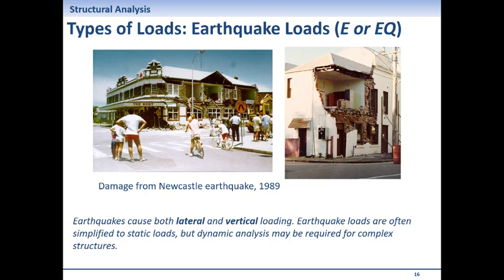Stress is something that happens inside a structural element. You've got a beam, you push it down, it flexes, and then not any stress, but flexural or bending stresses start to develop. That's a stress. Stress is always inside the material. And that's why I refer to axial force, shear force, bending moment, these as internal actions. They do not exist. You do not see them. They are how a structural element responds to an external load.